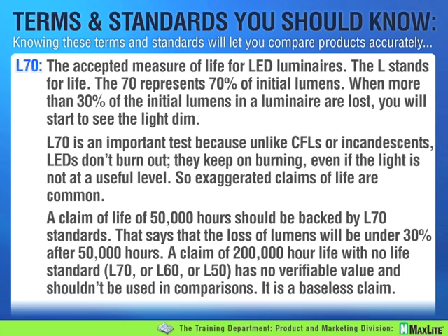So if somebody says it's a 50 or a 25 or a 60,000 hour LED product, one has to ask, what happens? Is it L50? Is it L70? They're not giving you the actual life if we're just saying the number of hours. So remember, with LED life, you need to combine the L number, the depreciation number, as well as the life claim.